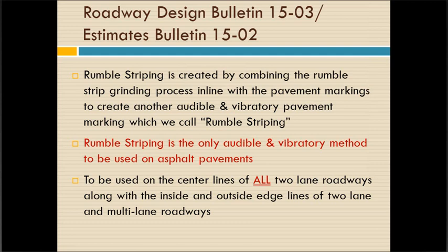Now, rumble striping is created by combining the rumble strip grinding process in line with the pavement markings to create another audible and vibratory pavement marking, which we call rumble striping. We're using it specifically on all asphalt pavements that meet the audible vibratory policy. So where we used to use an audible vibratory marking, which was profile thermoplastic, we're now using rumble striping.